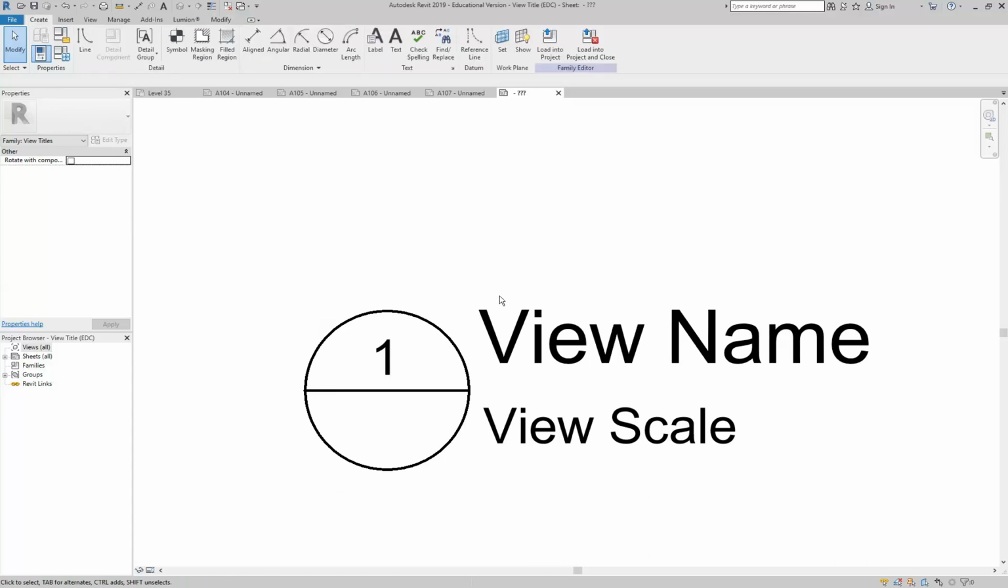So now comes the slightly advanced part, making your own label. And this is one of the main capabilities of Revit, the fact that you can have labels that are parametric. In other words, text, that's parametric, as opposed to just text that doesn't change. So if you're wondering how they have some text that you can change and that changes as you do things, it's all done with these things called labels, not text.